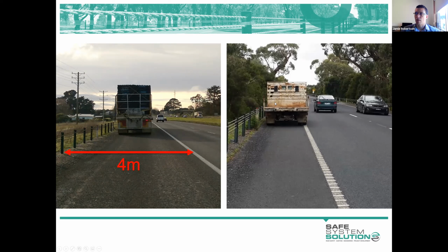We can't tell how long that barrier is. It may be that it's a fairly short length, and someone's just made the unwise decision to stop next to the barrier when they could have stopped at either end of it. But if that is a very long length, we should be providing refuge bays to provide opportunities for people to pull over safely, or desirably, we should be providing at least that 3 metre offset if we have the space available.